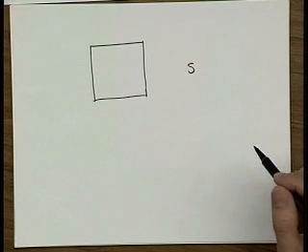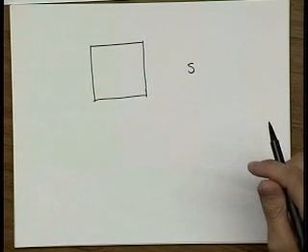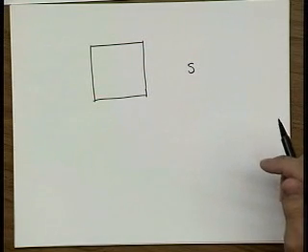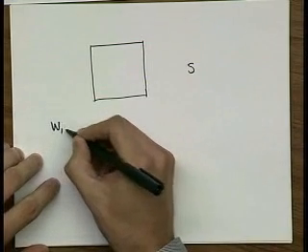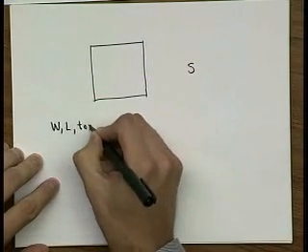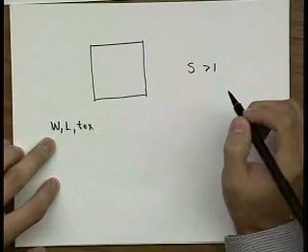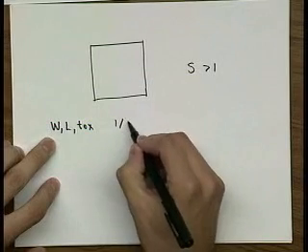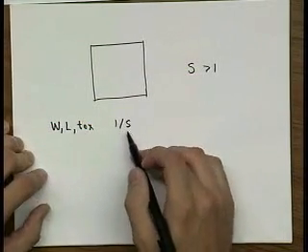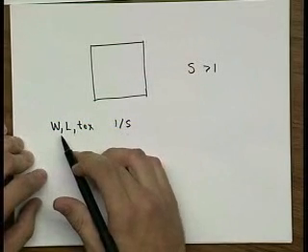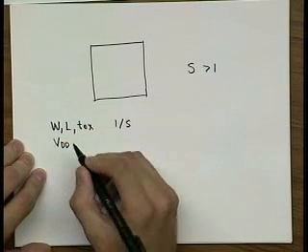But now, as an exercise, now that we know about models for various parameters, let's see what's going to happen if you just keep scaling all the parameters. Let's consider scaling dimensions W, L, and T_ox, and over time, let's assume that S is greater than 1. So over time, W, L, and T_ox for the next technology generation are going to be 1 over S of the previous generation, due to the compaction in the manufacturing process.